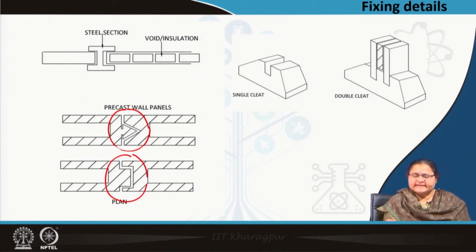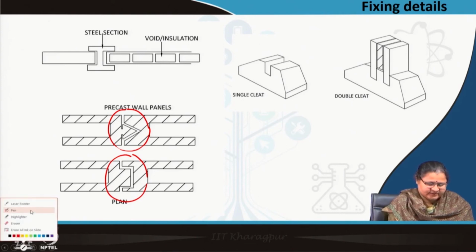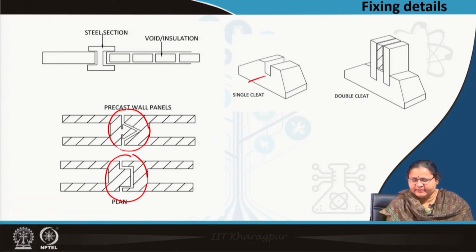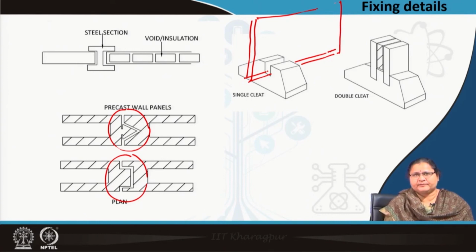Coming to the cleats, how it rests on the floor. These are cleats, these are supports made with concrete onto which the panel is resting. So, the panel will be passing through this and it will be resting. There may be another cleat after some time. So, this interval, this overhang, etc., are to be calculated out.